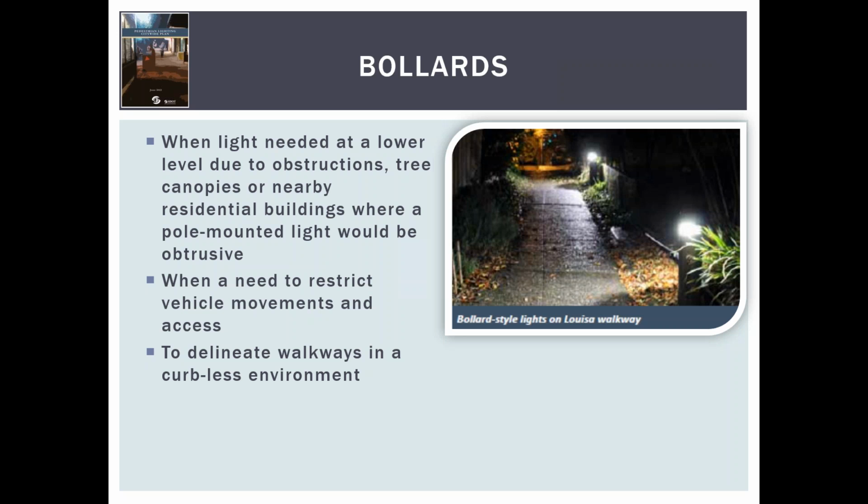You're not going to need the lighting levels on a trail that you would at a street crossing, because you don't have that conflict between automobile vehicles and pedestrians on a trail where automobiles are not there. But the trails offer more opportunities for adaptive lights, to either have less lights during the evenings and the very early morning hours, or to have a system using LEDs that provides the light to come on as the pedestrian is detected, and using solar power, which means that you don't have to, many times just providing power to an area is one of the bigger costs.